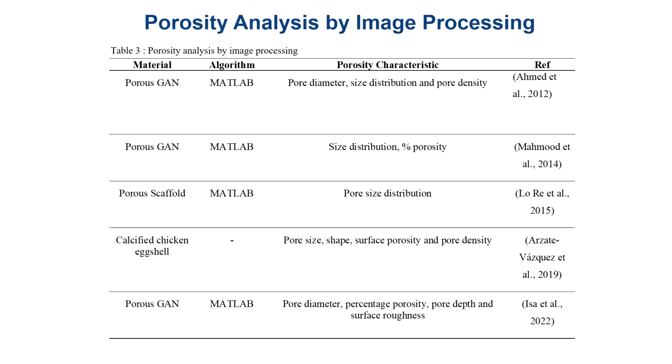For porosity analysis, accurate measurement and characterization of porosity are crucial for understanding the behavior and performance of porous material in various applications. However, traditional methods such as mercury intrusion porosimetry and gas adsorption have been widely used but come with certain limitations, as it is a destructive technique and requires specialized equipment and is not suitable for in situ measurement.